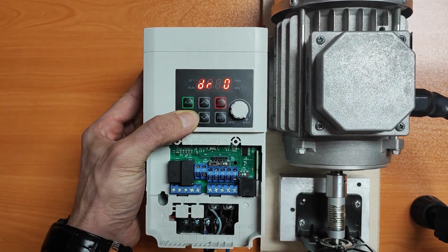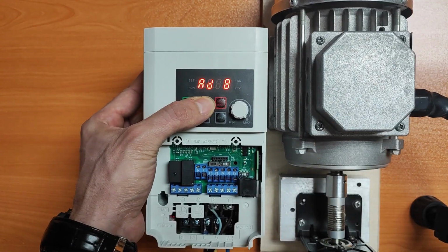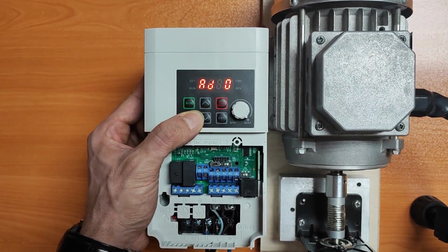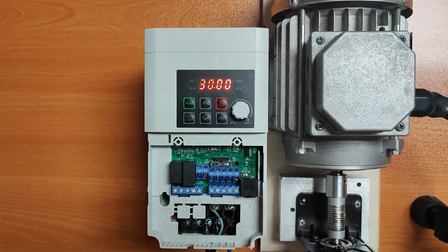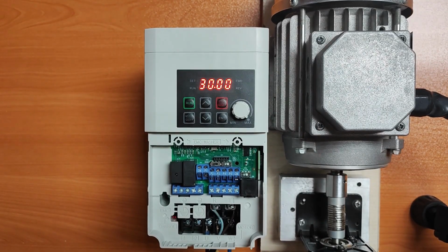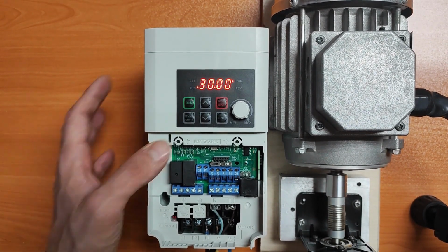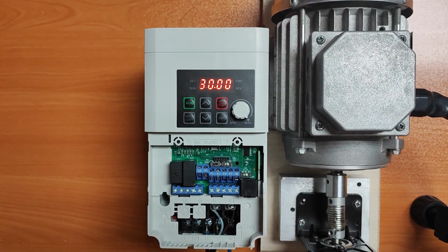Okay, the next stop mode is AD8 set to 2, which is via free run. In this mode, based on the load inertia on the electric motor shaft, the electric motor begins to come to a stop. Right now, my load inertia is low, so my motor should stop more quickly. I'll start the inverter. I'll stop it again. You see, because my load inertia was low, my motor stopped faster. So in the last option, depending on your load inertia, then after the stop command, your electric motor will begin to stop.